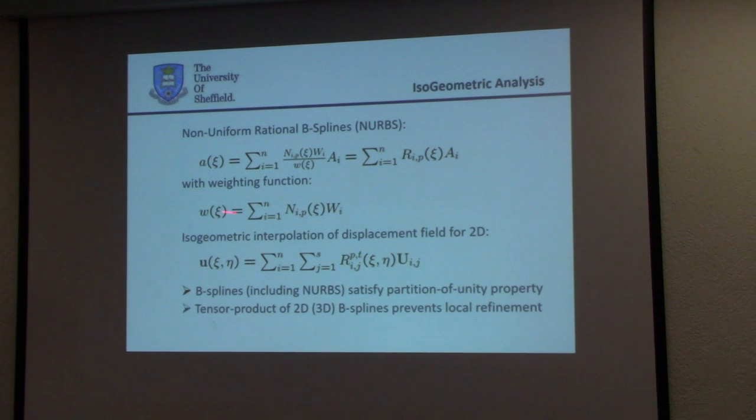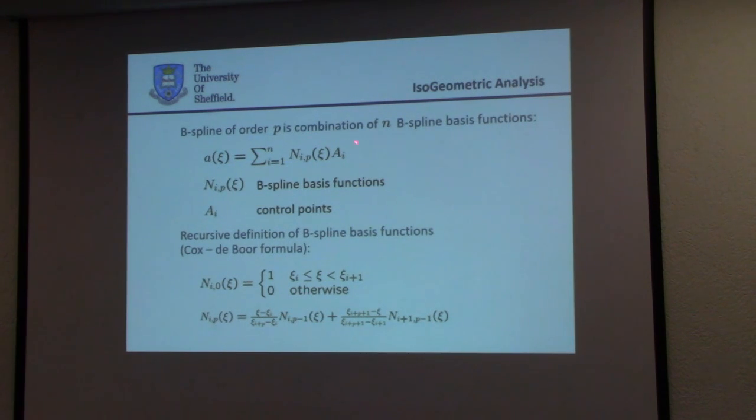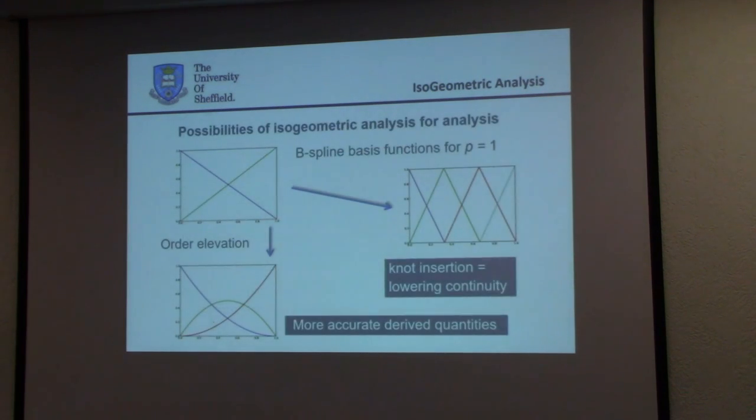Now, B-splines and NURBS are essentially defined in one dimension. How do you do 2 dimensions? How do you do 3 dimensions? Well, do NURBS in each of the directions. So you just make a tensor product in 2 dimensions or in 3 dimensions. You just have a NURBS in this, times a NURBS in this, times a NURBS in this direction. So then, for 2 dimensions, you get a double sum. For 3 dimensions, you get a triple sum. Times here the parameters, which are these control points. In 1 dimension, sorry.